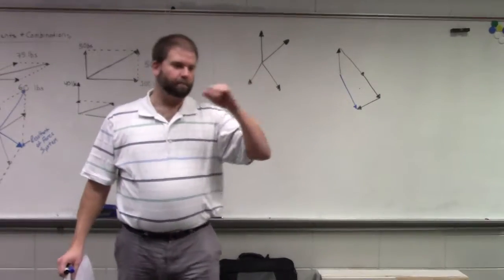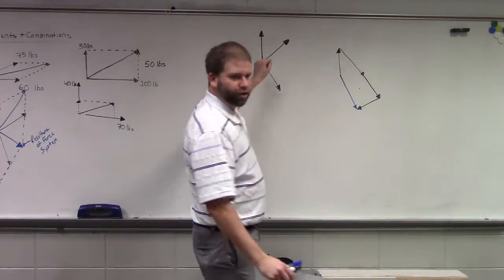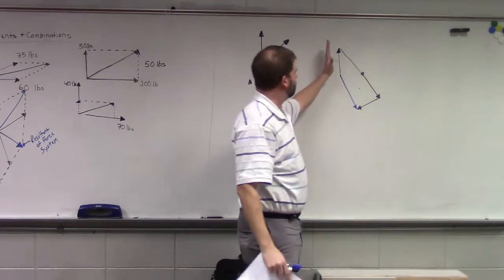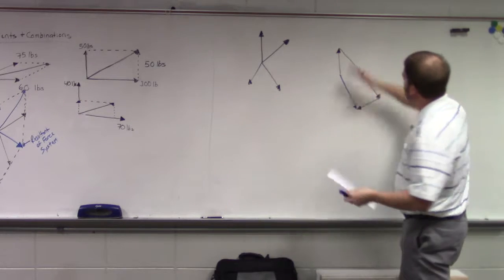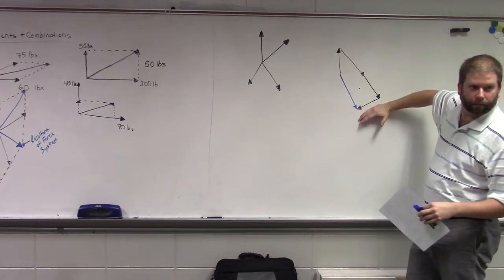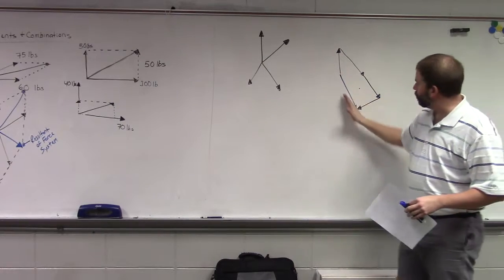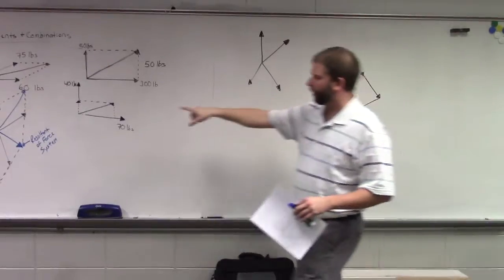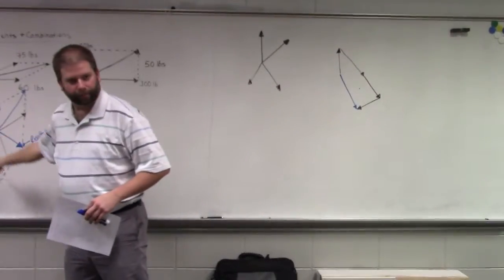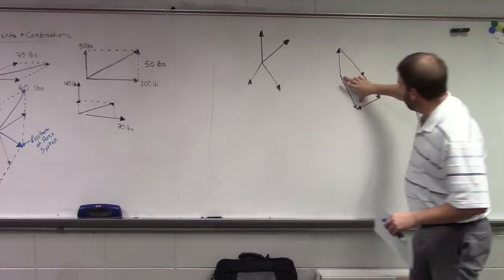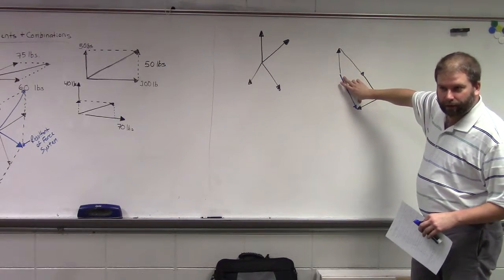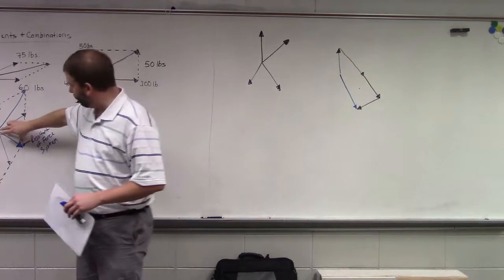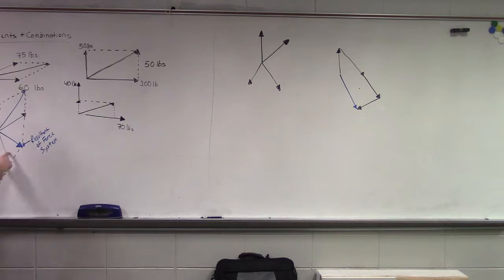So you're just blowing apart all your loads, saying they're no longer at one point. Got one guy here, one guy here, one guy here, one guy here. Then how we join them. Had I taken more care with drawing my system, the line of action and the magnitude of the force to close the polygon will be identical to the resultant that you get using this system.